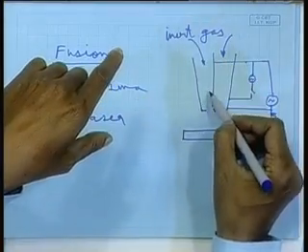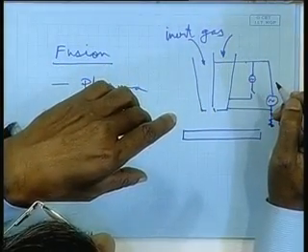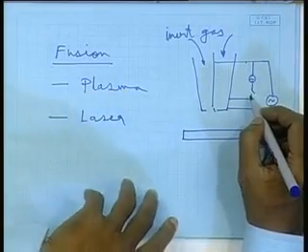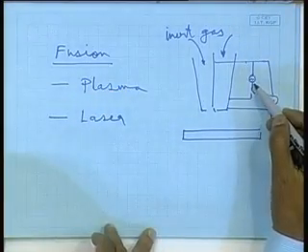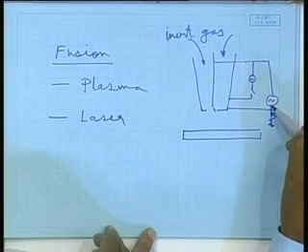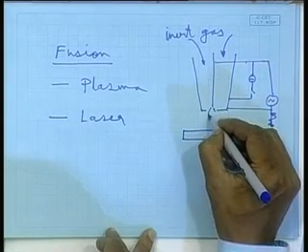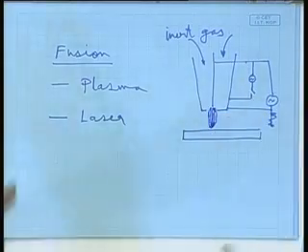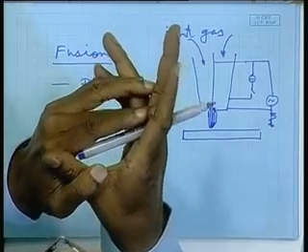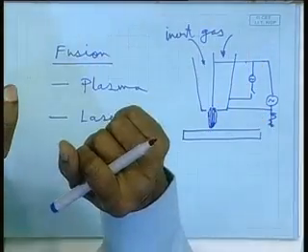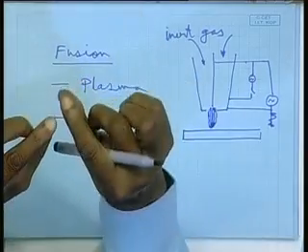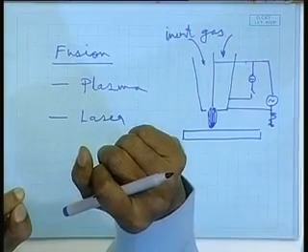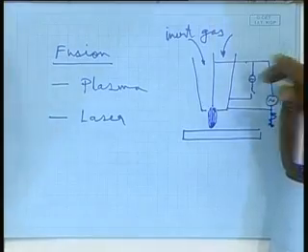In that arc, this inert gas will get ionized, right. The moment the ionization takes place, that high frequency source is switched off and the normal source is switched on. So, thereby I attain a continuous plasma column, as if a plasma flame, as if a gas flame. In a gas burner you have a gas flame, in a plasma torch I have a column of plasma, right. So, that means it again behaves the same as a gas burner, as a gas torch, right.